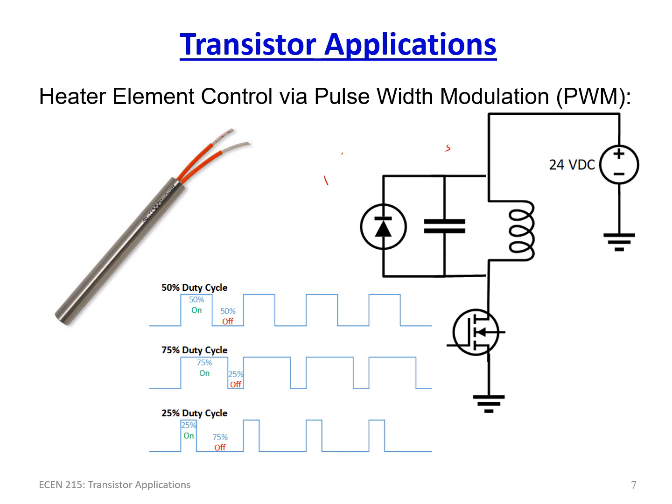Same thing here if we go to 75% duty cycle. By simply increasing the time on, the total time here is still 1 millisecond from here to here, but the amount of time on has now increased. And of course, at 100% duty cycle, it's just always on. And 0% duty cycle is always off. And so you have this linear range between 0 and 100% that you can control a lot of different devices, including heaters. This is extremely common and something that you will most definitely see in your career.